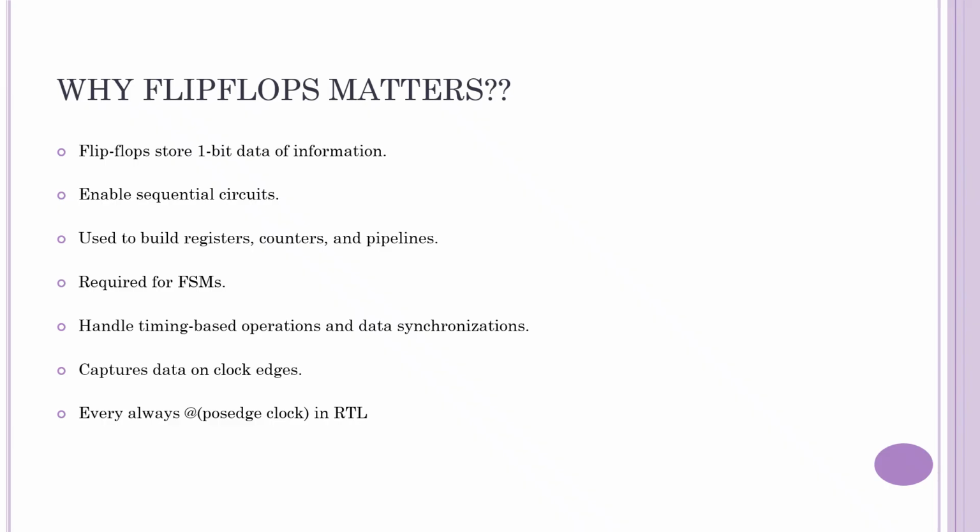Fifth, they synchronize everything with the clock. Flip-flops work with the clock edges, rising or falling. They ensure data is captured at the correct time, glitches are avoided, and signals are synchronized. That's why in hardware design, timing is everything, and flip-flops control the timing.